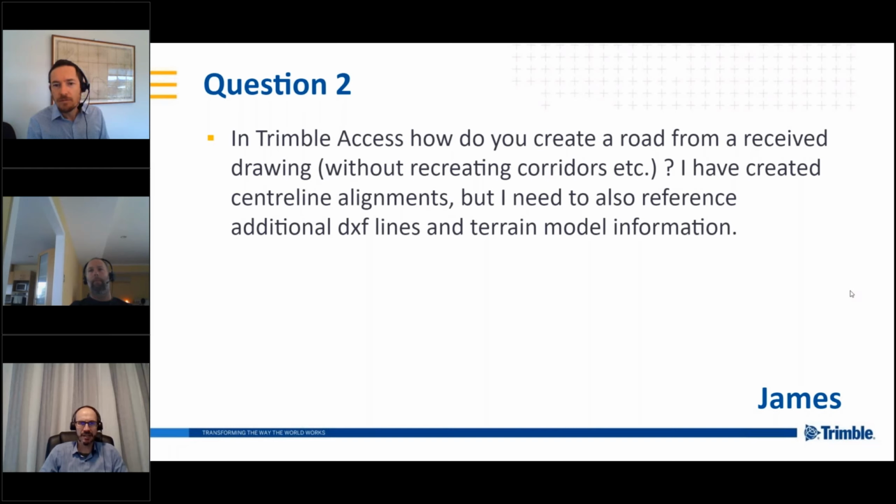I think there are a couple of other packages that can export that as well. And also we can convert 12DA files into a GENIO format. So you can take a 12DA file from 12D, and then we've got a little utility which can either be run on your desktop, or it can be run on the controller itself to convert it into a GENIO string-based road design.